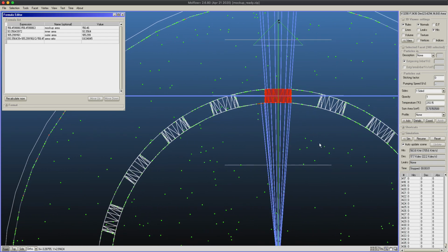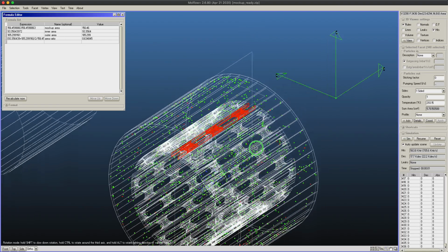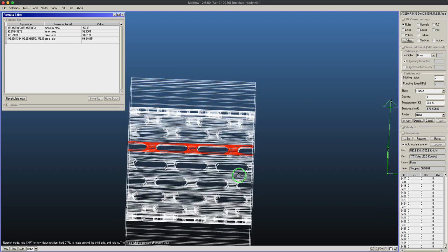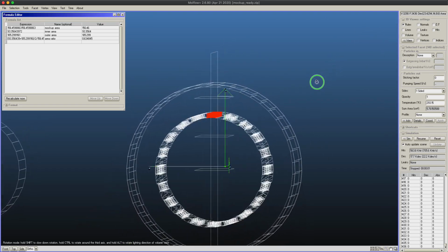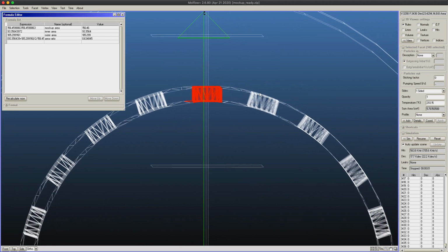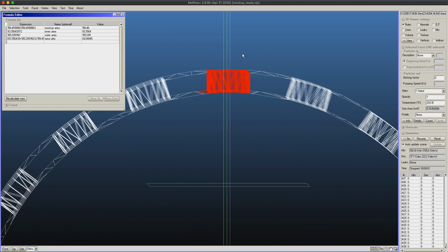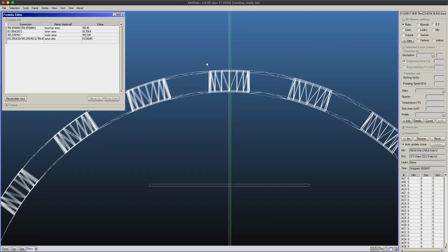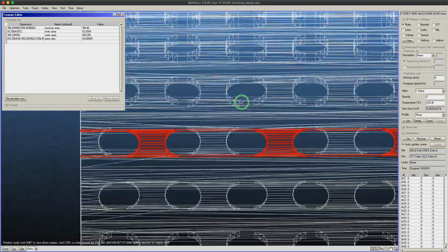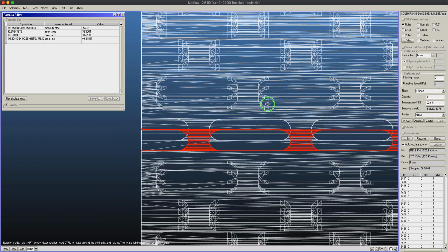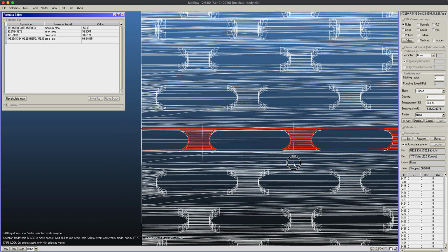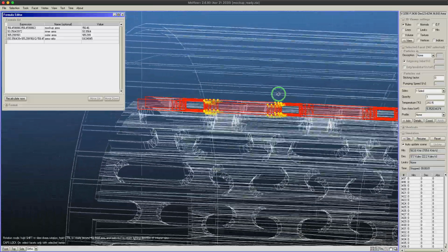For that, you will do the modeling of one single hole and try to get its transition probability. So I have selected the top hole, and the reason for that is that you can see that these sides, they are curved. So if you would like to do a transmission probability calculation, you would need to do a curved target facet and a curved inner facet. It's possible, but first we will see how we can simplify our life, and for that we will simply select the top hole. Now I will manually deselect everything, I will just use the vertex selection mode, so I have selected all the vertices.